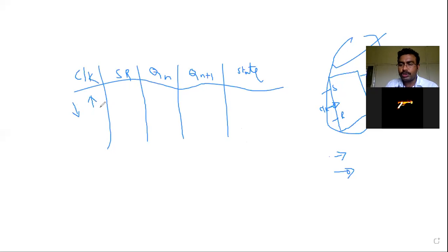That is our wish, to denote it as positive edge triggering or negative edge triggering, which doesn't affect the operation or output at all. You can trigger your SR flip-flop either at positive edges or negative edges to change its state. That is our wish. But for the representation of the clock, you have to show either positive edge triggering or negative edge triggering. You should show it like this, guys. For example, if I'm taking positive edge triggering, the clock should be shown like this.